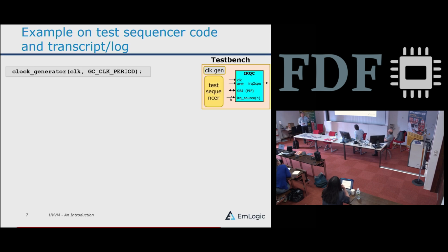But then you have the clock generator. And then you have your test sequencer that is basically going to test everything inside your device under test. And I'm just going to show you some of the main commands that you would use in any design here. So, for instance, you always should log what you're doing because that's important for debugging. It's important for anyone who wants to run that test bench.